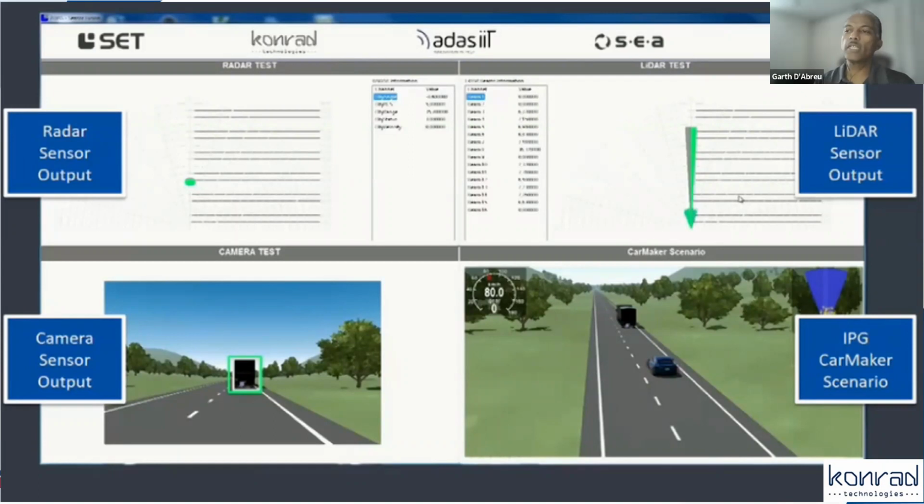And again, we started seeing companies that are introducing techniques where you can bypass the sensor and input signals directly into the associated module. So instead of having the camera look at a video image, you disconnect the camera and feed a video signal directly into the module so that you can create whatever video scenario you want artificially and input that to the module directly. And again, it's a compromise because you're taking it further away from the real world environment and you're removing the camera sensor itself. So if you have a camera that's immune to some RF environment, because you've bypassed the camera, that's a potential immunity that you're not going to be able to detect during the course of a measurement.